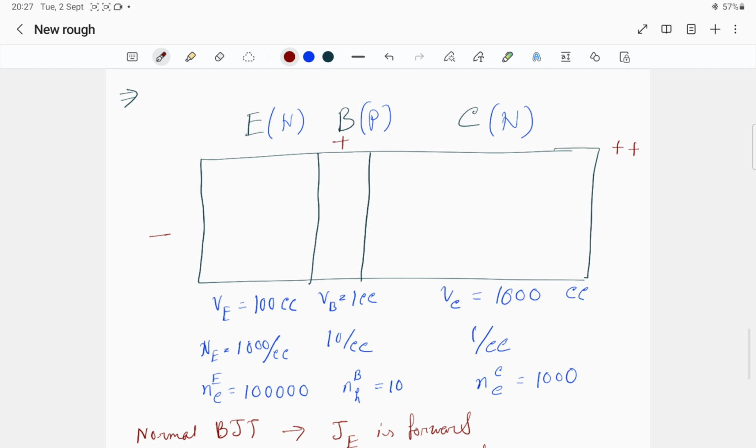Now if you look at the transistor schematic once more, for forward bias, if we just talk about electrons for now, we are forgetting anything else. We just assume for the sake of calculation that no hole is present in your device, right? Just for the moment. As it is forward bias, a large number of electrons will be injected in the base, right?